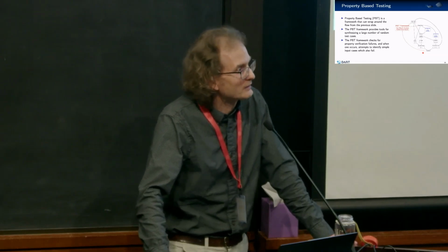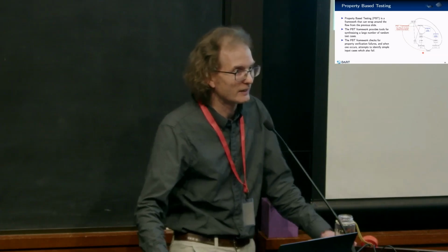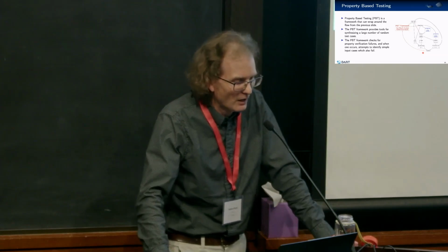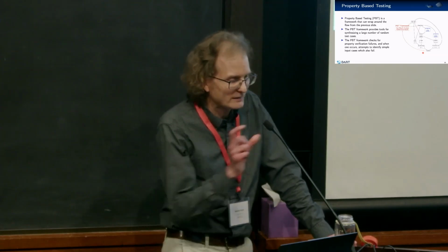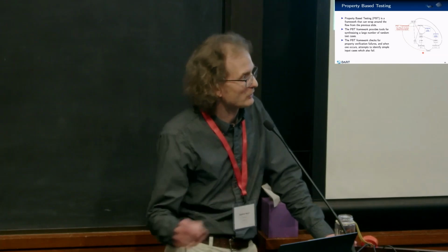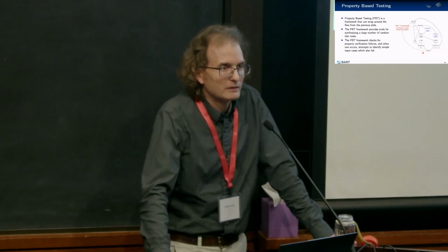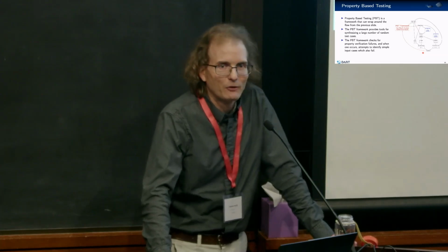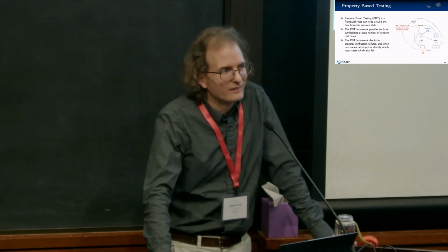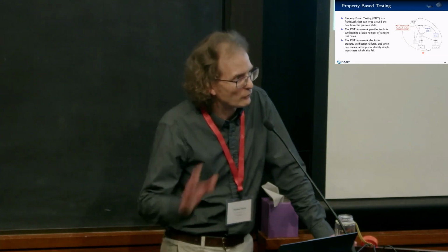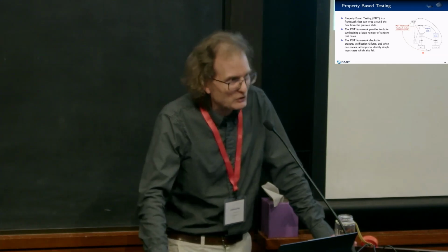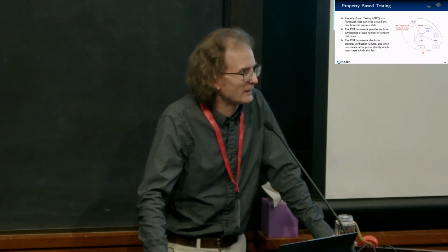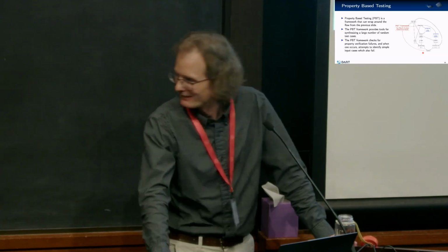It can make significant improvements and modify what the wire format looks like, and it's transparent to you because on the other side, when you read in your protobuf, it does the reverse transformations. But we wanted a definitional language that could specify exactly every bit in a register or a set of registers for these avionics, so that we could be confident we could bit bang those registers in the right way. That was the reason we selected Kaitai. It's very expressive and very specific for the specific bit patterns, and our tools are designed not to do any optimizations there.